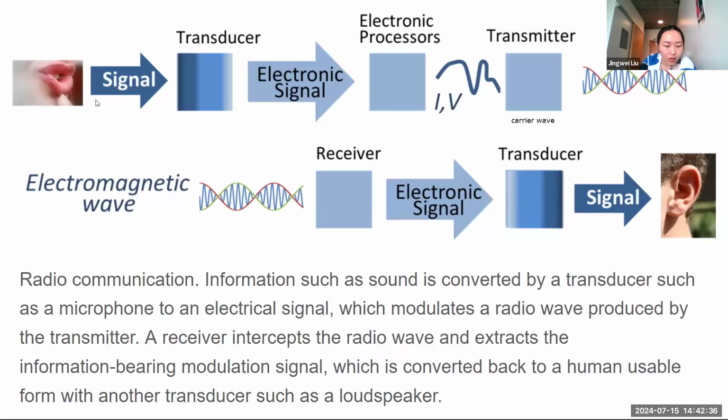Therefore, because you have this modulation signal generated by your mouth, like your sound, this electronic signal will be impressed on this carrier wave, and these two waves will be, not really simply added together, but there is some modulation process, and then it will generate this kind of wave. So this is actually called amplitude modulation, AM. So we know there is amplitude modulation, AM, and frequency modulation, FM, right? This is the radio. If you listen to radio, you know AM and FM. So this is what it means actually. So this is generating some amplitude modulation, and actually here this high frequency wave, right?